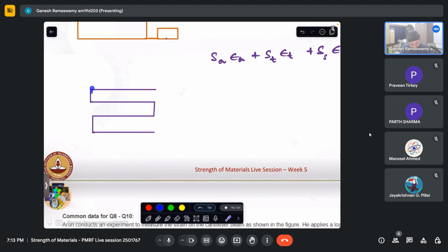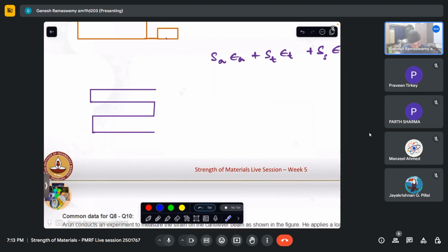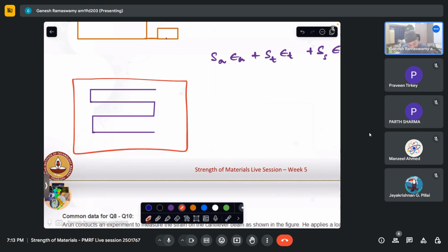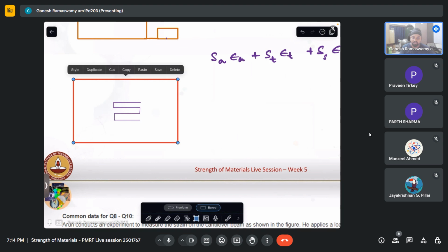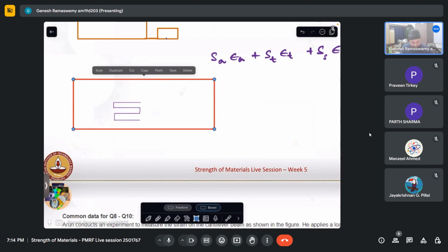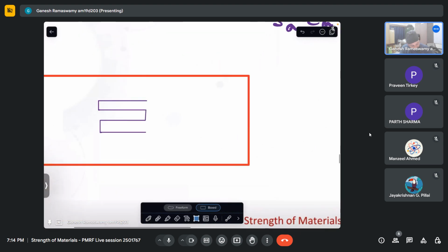But we saw in a component, when I pull it, if this is pasted onto a component, let us say, and I minimize its size like this, initially it is like this. Now when I pull it, it will become like this. So there will be a transverse reduction vertically also because of the Poisson's effect. So what will that do? That will reduce the length of this. But we are measuring only along the length. We don't want that to come into our picture.